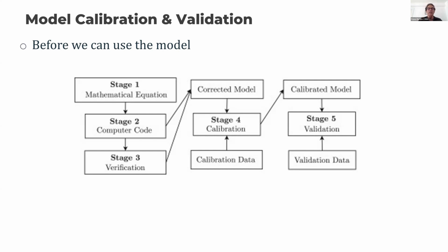Usually what we do is first, before we calibrate, we do a sensitivity analysis of all the parameters of the model, we try to identify those that produce more changes in the model, those that the model is more sensitive to. And then we run many times the same problem, with different sets of parameters, and try to see which set of parameters gives the best results, comparing it with the measurements, okay? And then, so this is stage 4, it is the calibration, okay?